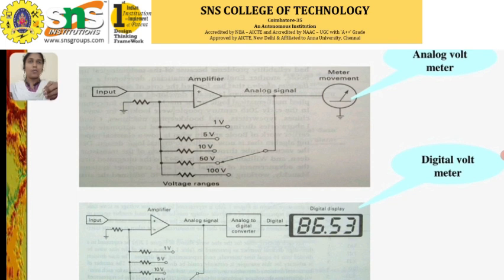An analog voltmeter measures voltage by moving a needle across a continuous scale, where the needle position corresponds to the input voltage we are giving. It relies on magnetic or mechanical components, making it sensitive to calibration errors, vibrations, or parallax when reading.